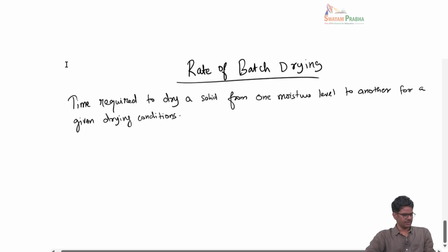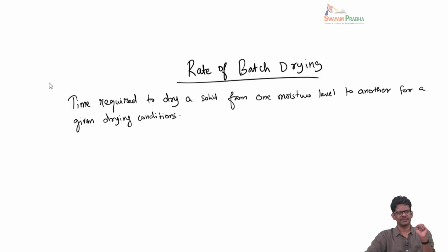Now, drying is a little bit difficult to theoretically predict. Okay, this is because the solid substance that we want to dry could be made up of different kinds of material. Okay, it can be organic, it can be inorganic. The microstructure in the solid can be very different, and the chemical makeup of the solid is different, and how the composition of this material interacts with water is also very different. So because of this, we don't have a very good theoretical understanding of how to predict drying kinetics.